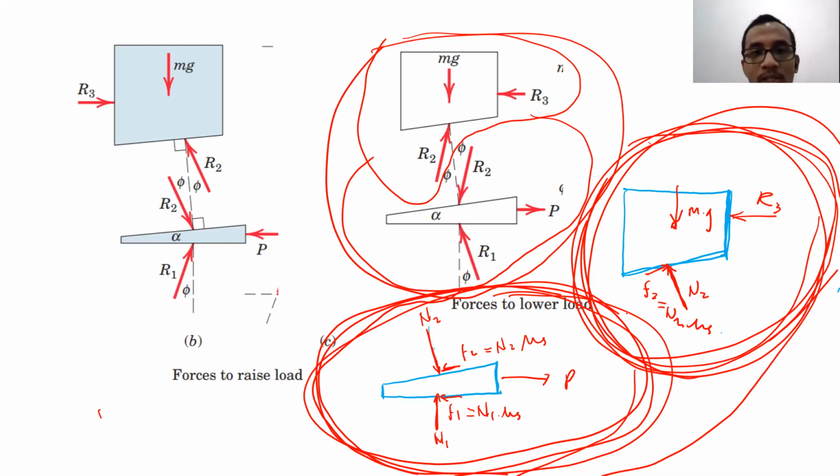But for sure, you have to remember that friction force and normal force are just one unknown, because the friction force is normally the normal force multiplied by mu, depending on the condition. If it is said from the beginning that it is in motion, then the friction force will be the normal force multiplied by mu k. But if nothing is mentioned, then the friction force will be equal to the normal force multiplied by mu s.